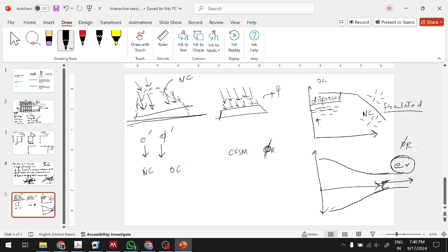Okay, so here we are talking about the cohesion, isn't it? If we talk about cohesion in this state, your NC clay may have a cohesion component at critical state, but what it is trying to say is that cohesion and friction angle that we have defined in classical soil mechanics is not a fundamental property, and it depends on NC and OC.